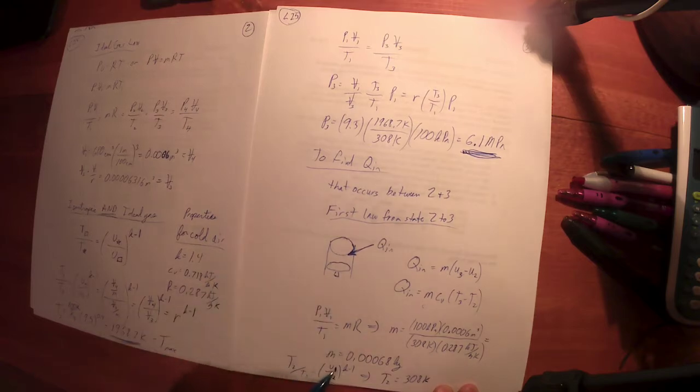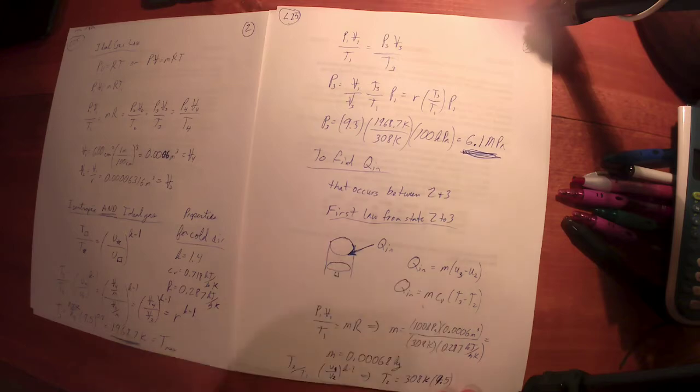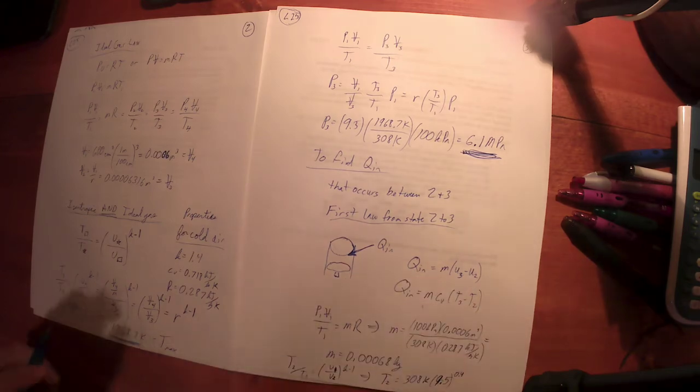You invert the other side. So if it's 2 over 1 here, it's 1 over 2 there. And this is a max volume over a min volume, so this is multiplied by the compression ratio, which I'm just going to write as 9.5. You could write R in there and plug it in later. That's 9.5. K is 1.4, so to the K minus 1 is 0.4 power.